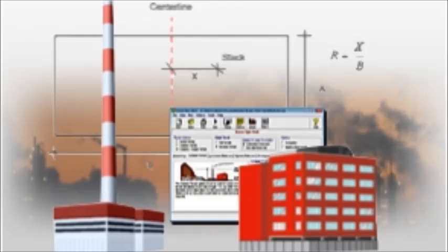Due to the expense and time to run an air dispersion model, often an initial screening model is run. This model assumes the worst case weather and makes a prediction without the need to buy meteorological data. If the results from the screening model are acceptable, then there's often no need to go to the expense of running an air dispersion model with full meteorological data.